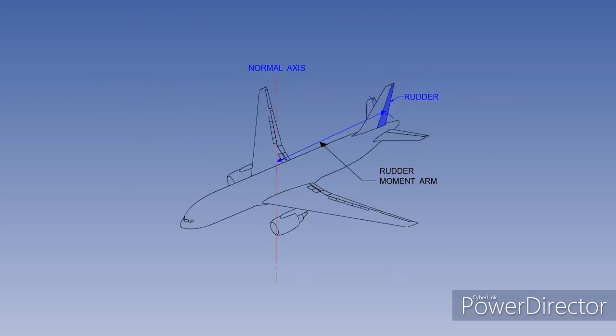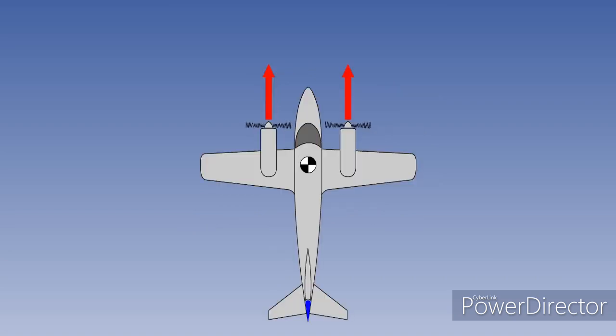The rudder gives directional control about the normal axis. The rudder is not used to steer the aircraft like a boat. The main use of the rudder is to balance the aircraft, to maintain coordinated flight, but in addition, the rudder is used to fulfill several other particular functions.